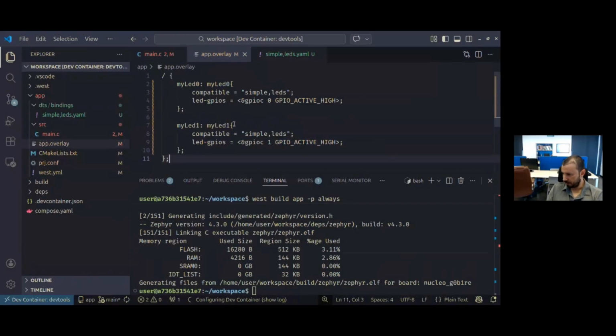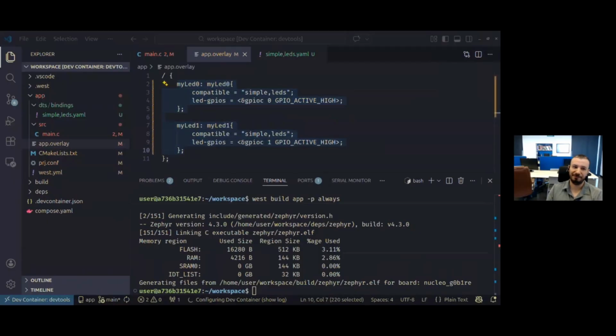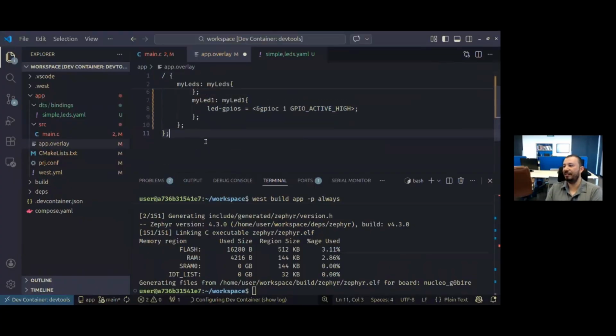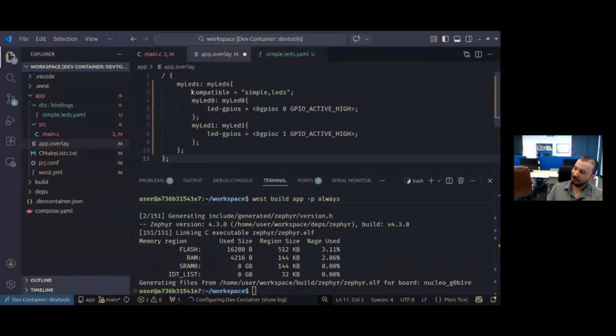So like you already had experience with Zephyr, no? The first driver that you've been using is GPIO, and probably the first binding file that you've been using is gpio-leds. And you will remember that to declare these LEDs, you have to use child nodes, okay? A new node that is part of the parent node, right? This is another way to declare your nodes.